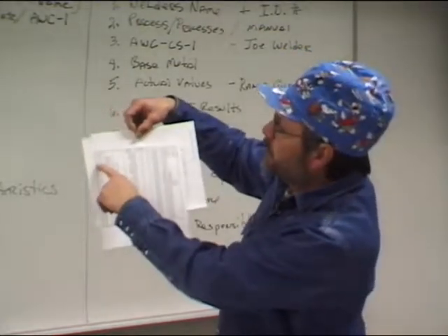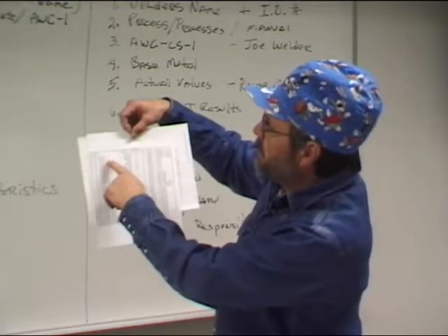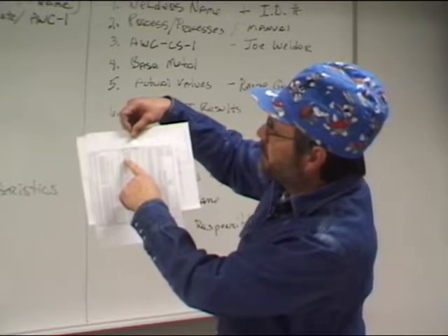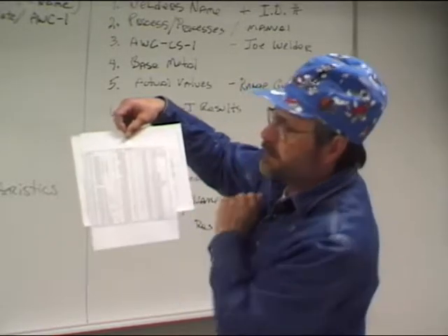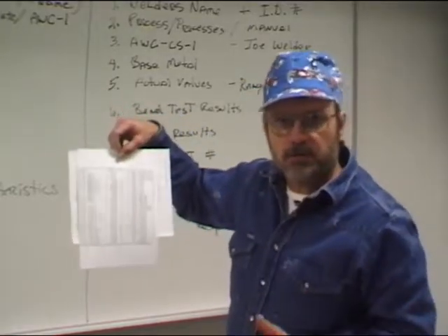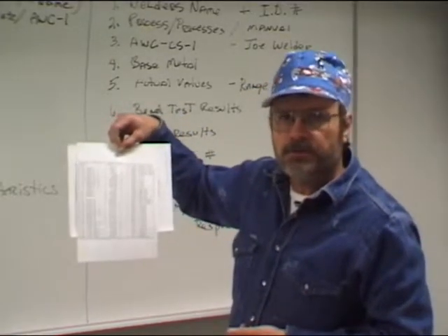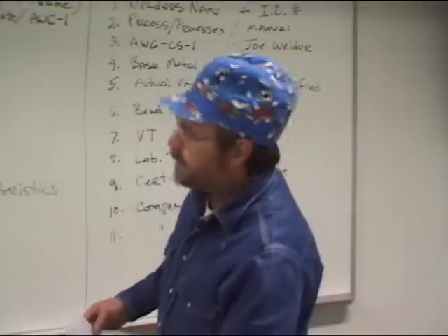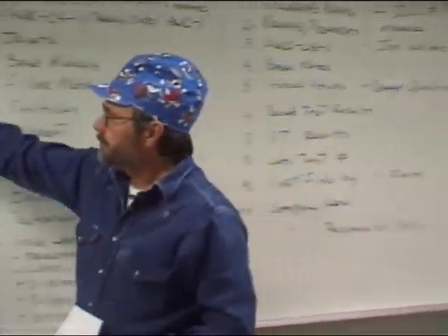So we know that we're using SA 106 Grade B. So where it says Other, you would write UNS number K03006. So it makes it easier to cross-reference the type of material that you're using. Okay, so that takes care of topic number 5.